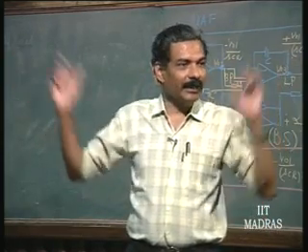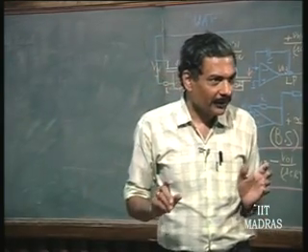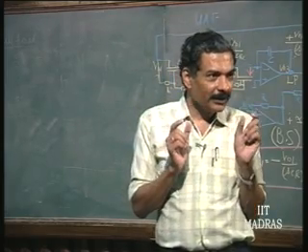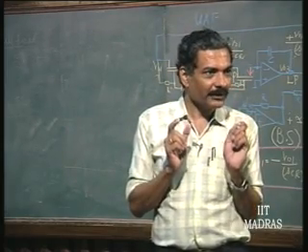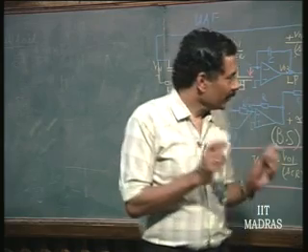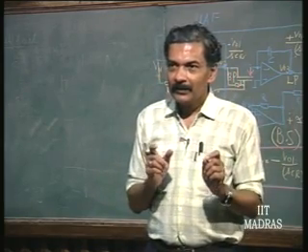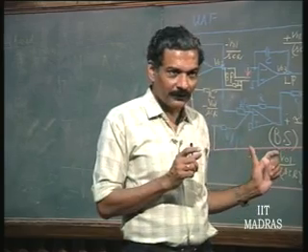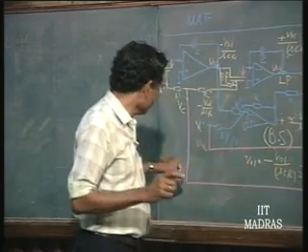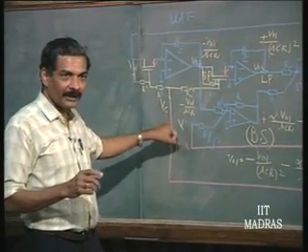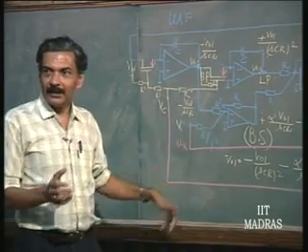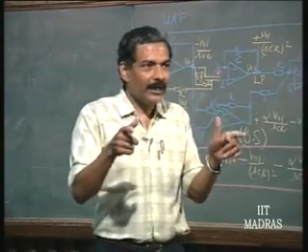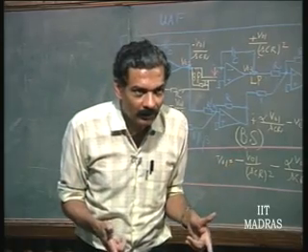We do not know who is sending our information from space, but we know that this information is a band limited, highly narrow band signal. So, you can keep scanning the entire range of frequencies using this kind of self-tuned filter. What you do is skip ranges by disconnecting VC and making it a sawtooth, and search in different ranges of frequency and see whether anything is getting locked.